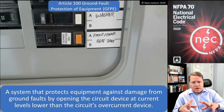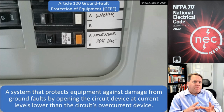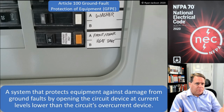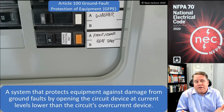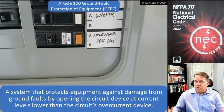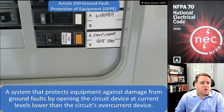So it is outdoor equipment. You don't want to put on a GFCI because a GFCI might actually trip the heat tape circuit, because the heat tape actually works by having a small ground fault. But you also want to make sure it's not going to burn the building down. So you install a different level of protection. We call it equipment level protection, ground fault protection of equipment, GFPE.